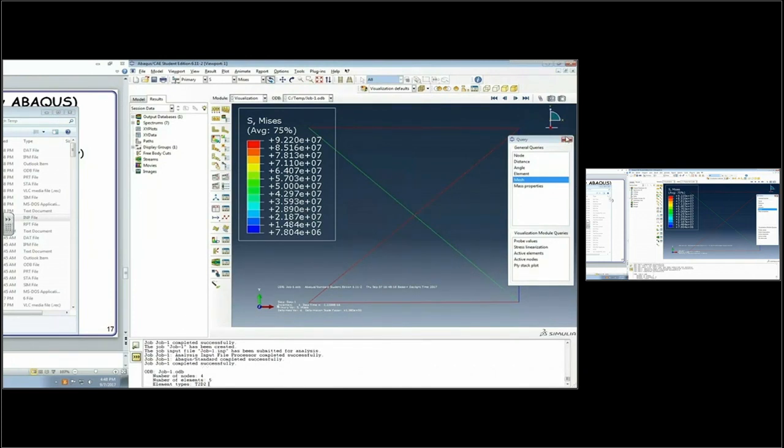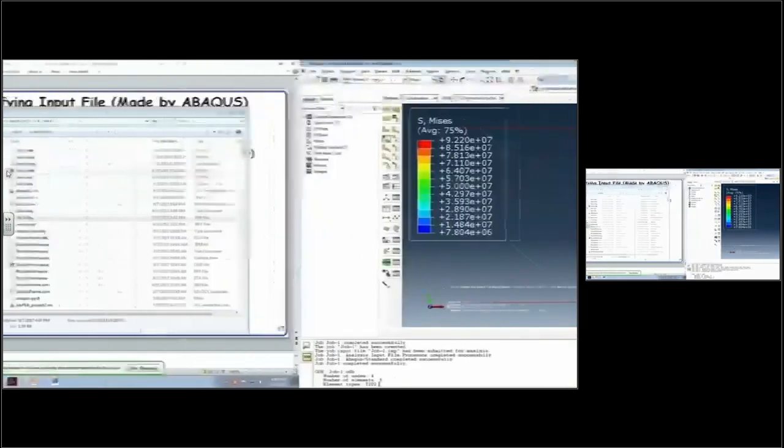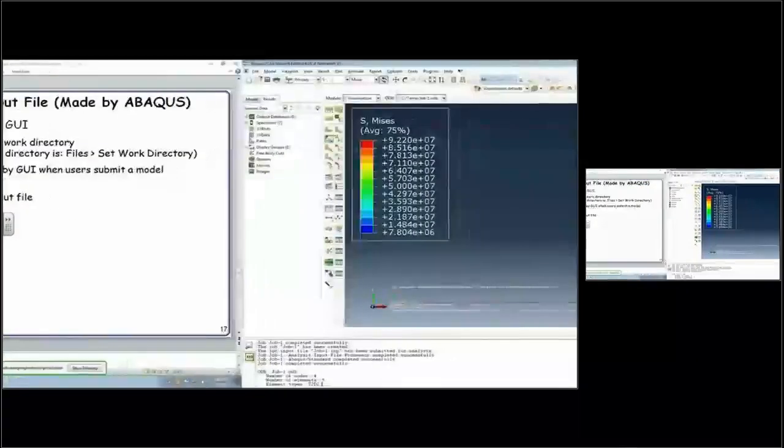So after removing this center node, we need to do the fully stress design. So we need to change the cross-section area of each truss, and then see how the stress changes and make the stress of each member getting close to allowable stress, right? First, let's check the stress.